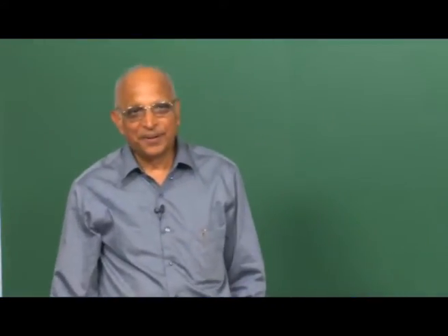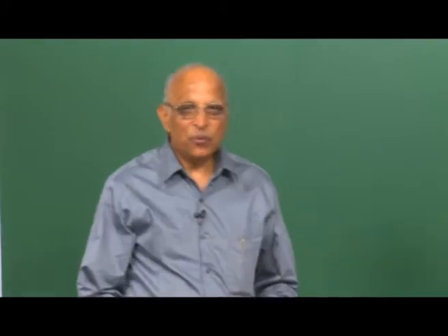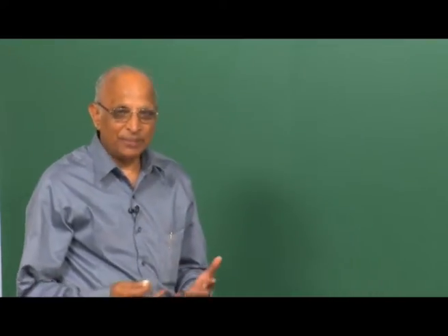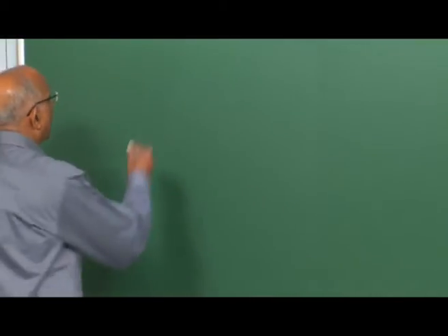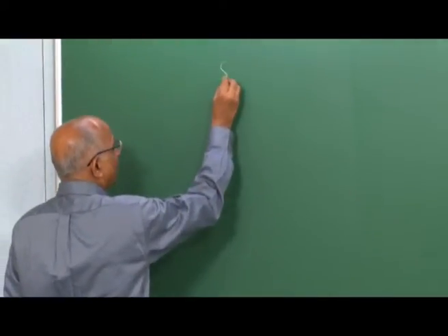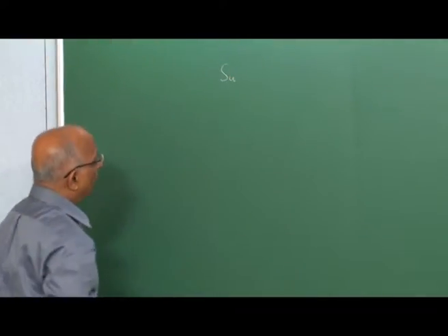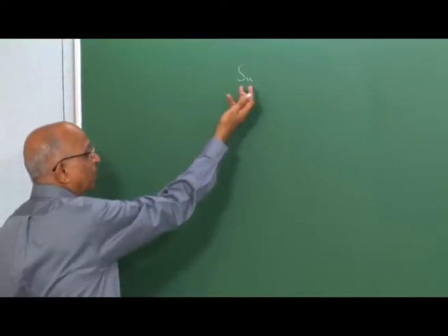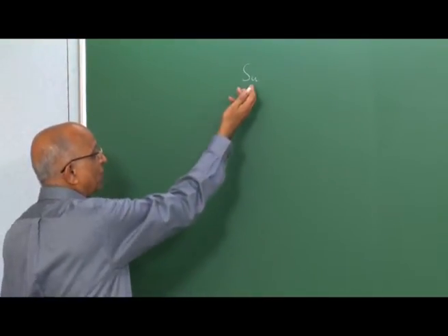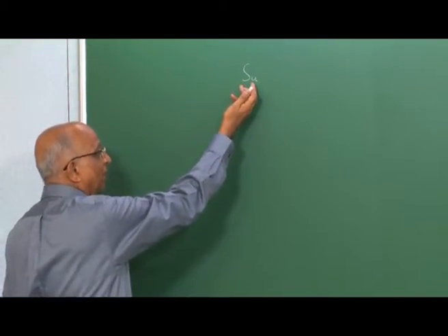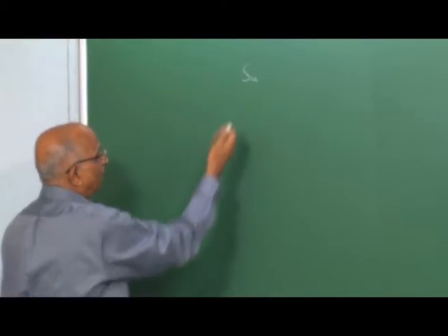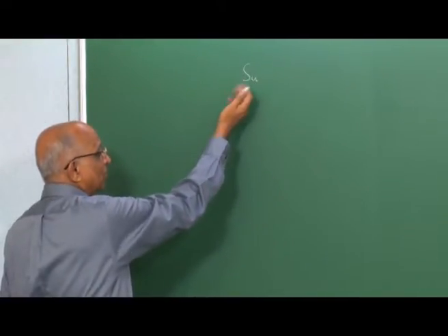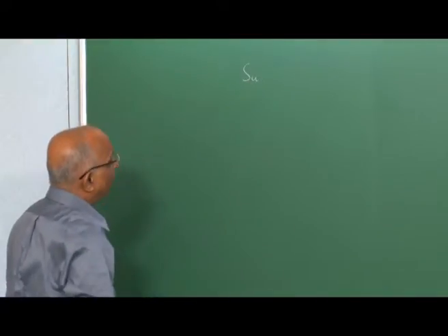Morning. We looked at a few parameters relating to these chemical reactions, and what did we take a look at? We looked at the burning velocity SU, also talked in terms of a flame speed which takes care of the burning velocity when the observer is on the ground. Burning velocity is when the observer is on the flame, that is with respect to the flame.